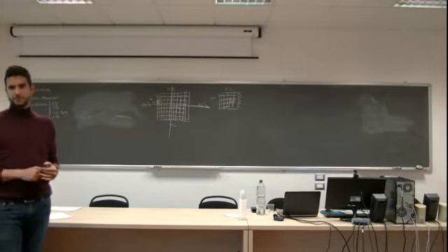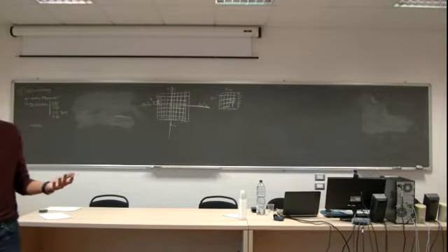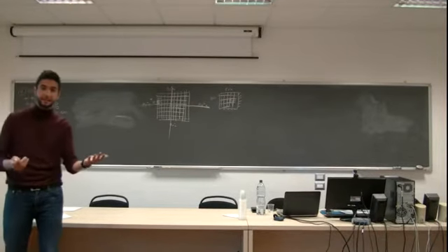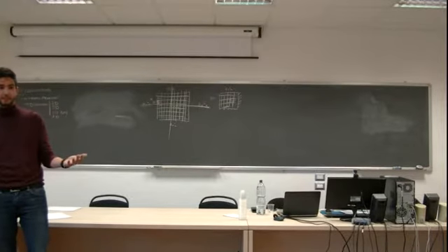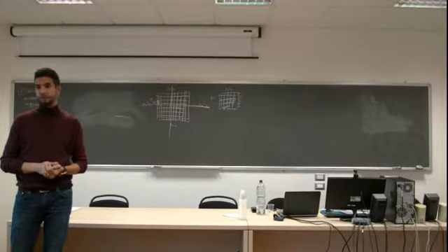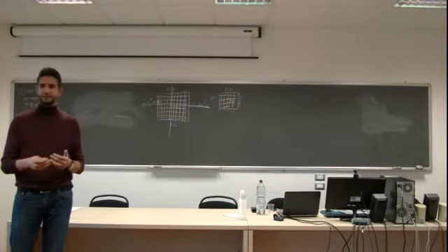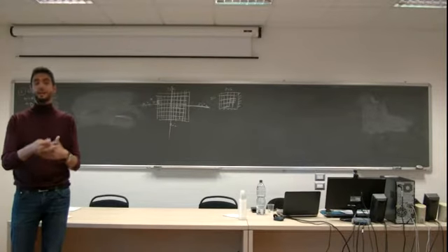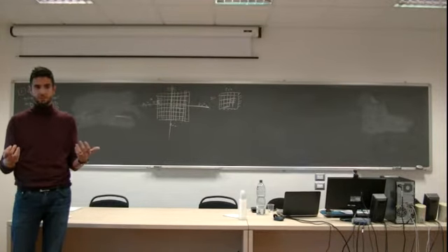Like, if I am simulating a room, I will always be between 15 degrees and 30 degrees, right? My thermal range is between 15 and 30. Do I need to apply thermophysical curves inside the model, or can I assume they are constant values?